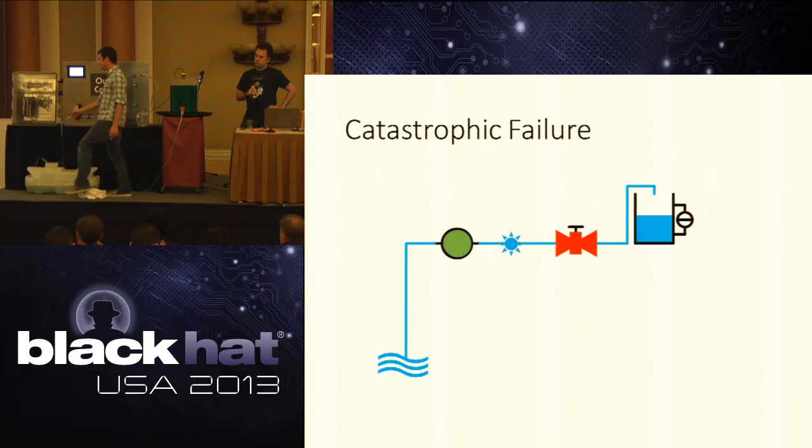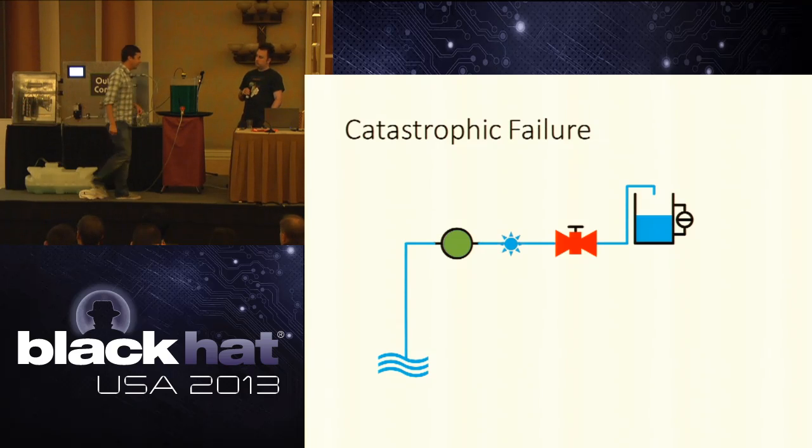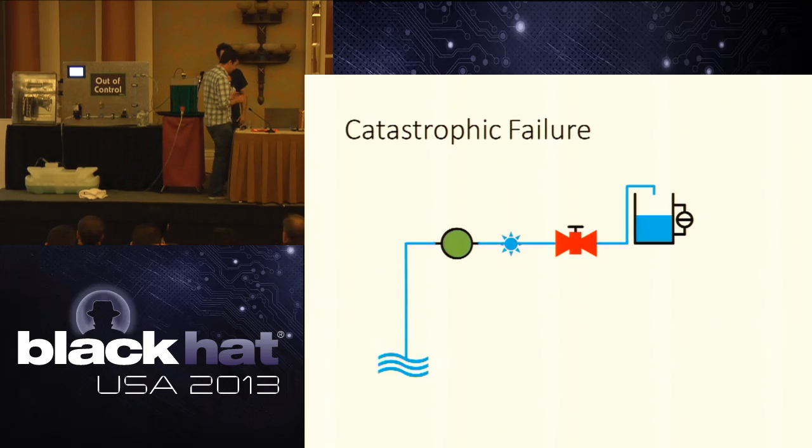If you drive these output signals directly, you could have logic sending commands to turn off this pump all day, but if we actually drive the signals in this PLC, it doesn't matter what the operator wants to do. It doesn't matter what the PLC logic wants to do. We're driving those outputs ourselves, and we'll get to see that. Yeah, let's do that. Okay.